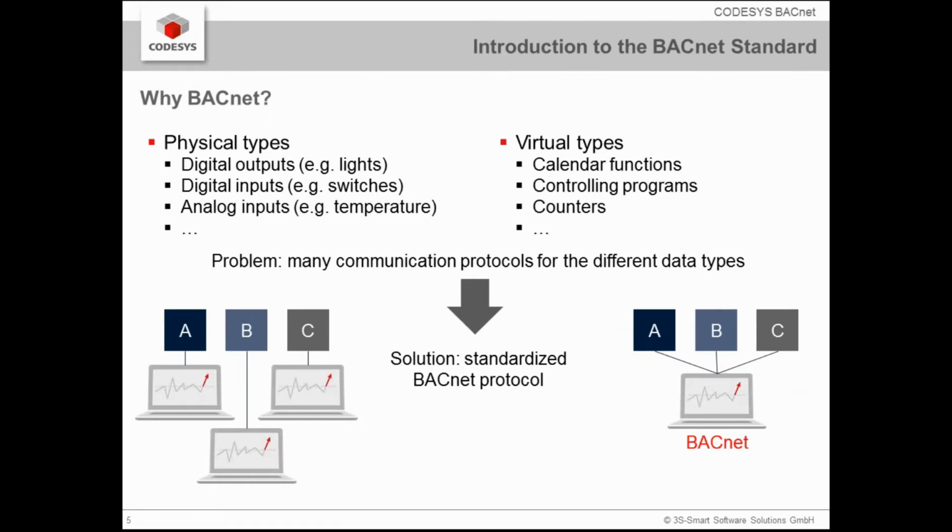So what was the motivation for BACnet? As you all know, there are a lot of different physical types like digital outputs, digital inputs, analog inputs, for light, switches, or temperature, and also virtual data types like calendar functions or controlling programs. And the problem was there are really many communication protocols for the different data types. And BACnet was meant to build up a solution as a standardized communication protocol.